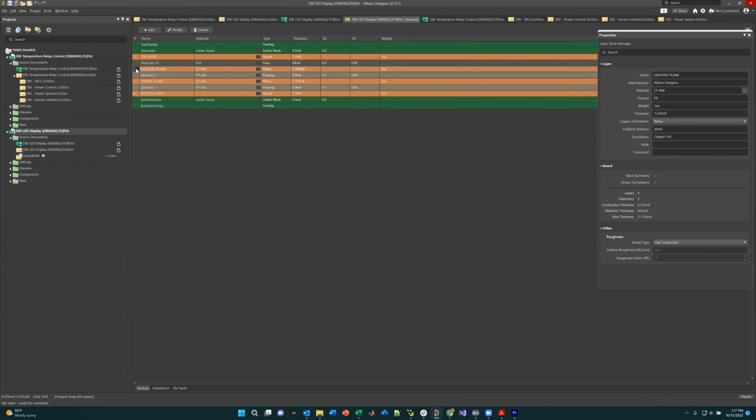To add layers, you just come here and go insert layer above or layer below, and it can be a signal or a plane or core and prepreg if you're adding in the insulation layers, which there always has to be an insulation layer between. You don't need to worry too much about the details of this. I can explain more about the different layers and dielectric strength for doing controlled impedance boards. That's where that really becomes critical.